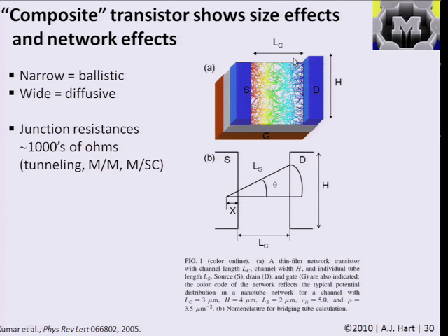And that's right. However, if we are, for example, in a regime where the density of nanotubes is low, or where the distance between the two electrodes is comparable to, say, the mean free path of electrons in the nanotubes, we see different aspects of scaling. We, in fact, see a combination between the quantum size effects of the nanotubes and the classical size effects due to the interactions between them, essentially between the structures and their boundaries in this network structure.